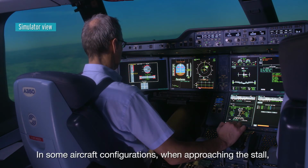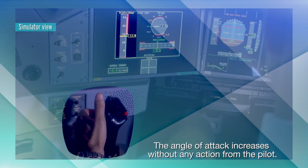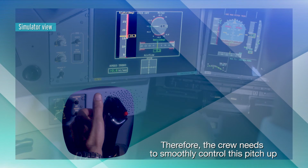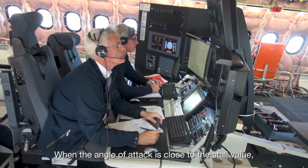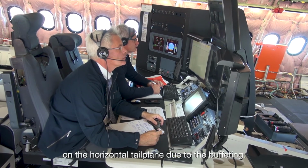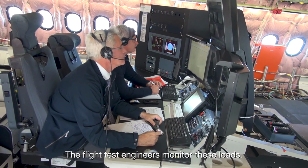In some aircraft configurations, when approaching the stall, there may be a pitch-up motion. The angle of attack increases without any action from the pilot. Therefore, the crew needs to smoothly control this pitch-up to maintain a progressive increase of the angle of attack. When the angle of attack is close to the stall value, there are frequently high loads on the horizontal tailplane due to the buffeting. The flight test engineers monitor these loads.